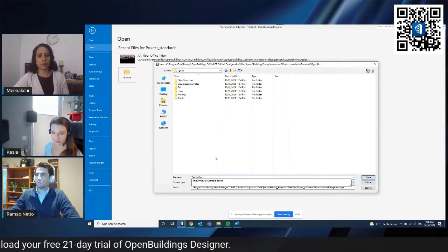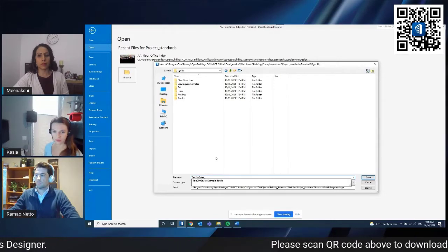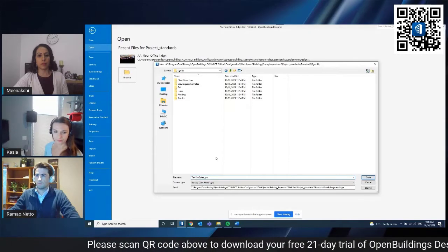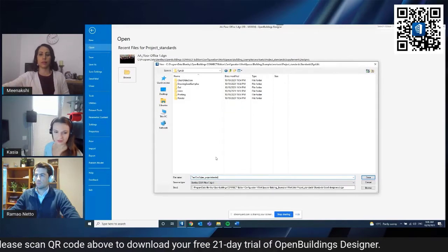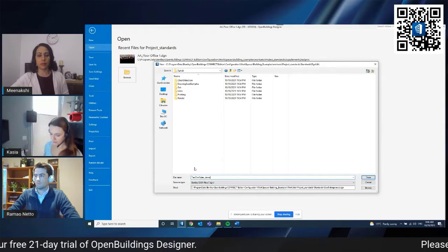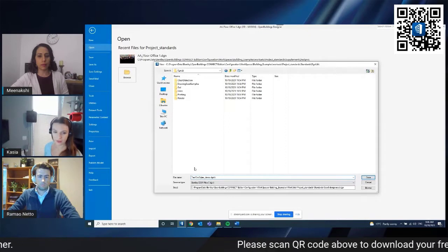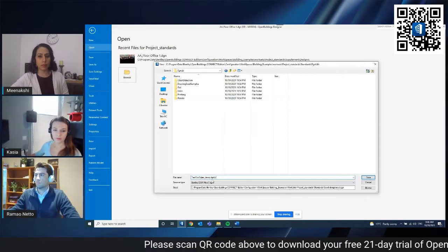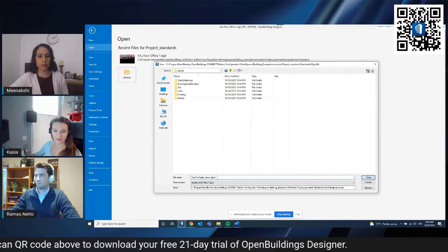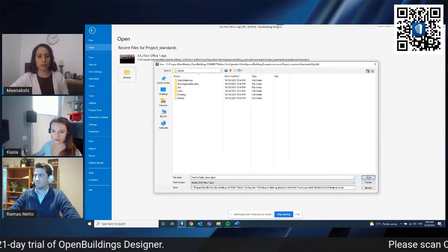The default name is text theme styles, but you can give a personalized name. So let me call it project standards, or the short demo. And then I need to add the right format, which is DGN lib. It comes from our standard DGN format, but the lib ending applies the library function to this file. So when I save it,